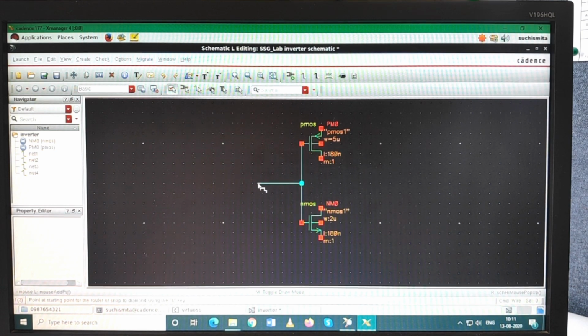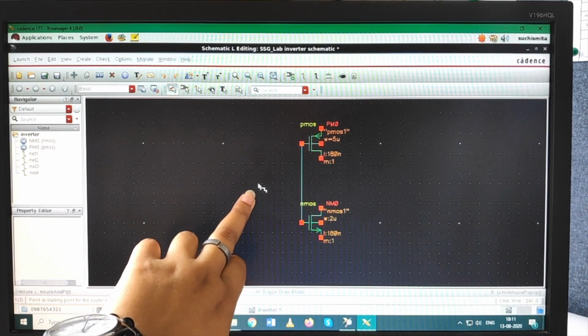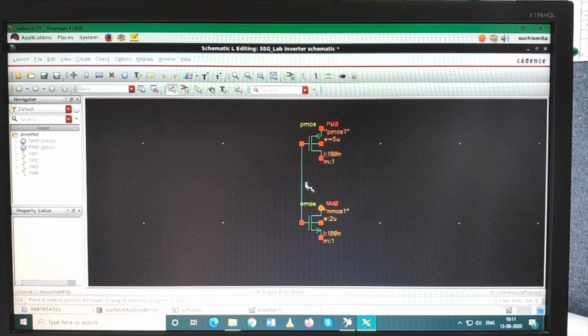Now see, what did I do? Gates are clubbed, but the input has to be connected somewhere, right? So single click on this wire, bring it outside to a particular distance, and then double click on the black screen. Done. The wire ended over there.